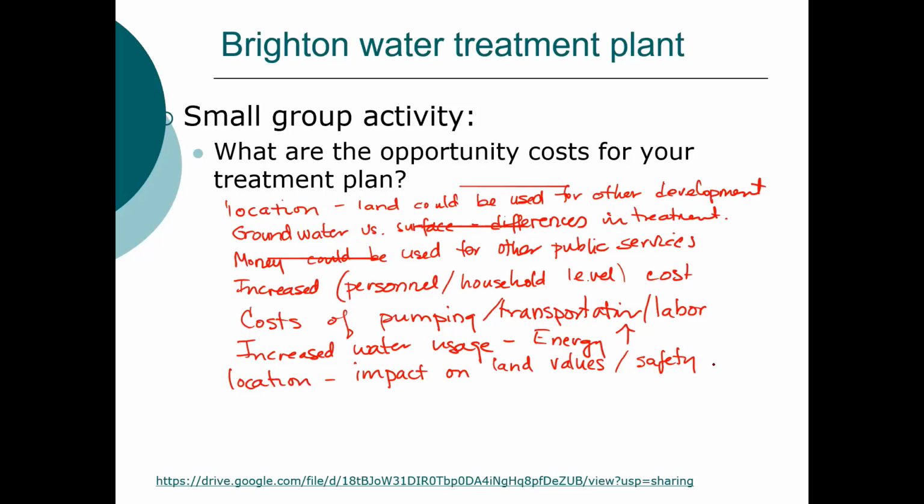So basically they were required to stop using chlorine gas because of the hazards of a chlorine leak. They now use liquid chlorine, so they use sodium hypochlorite for disinfection. It's more costly. It adds more dissolved solids to the water than chlorine gas. There was a trade-off in that, but the decision was made to switch because of safety. So you've got that aspect in terms of the homes. Anything else we can think of?